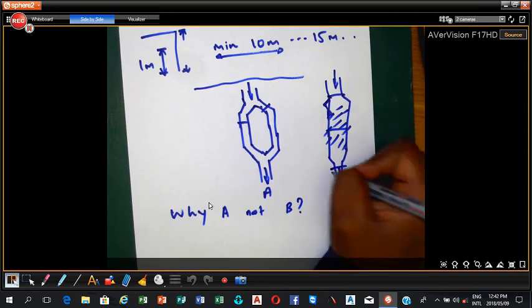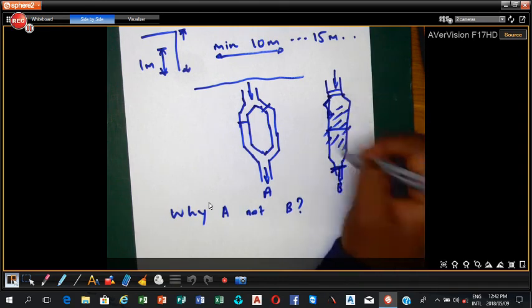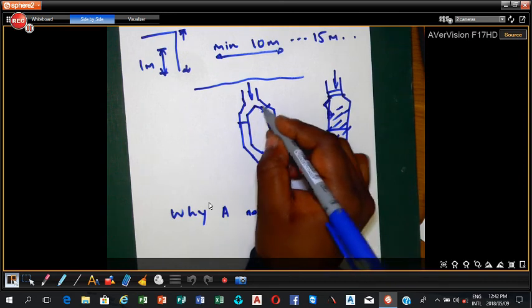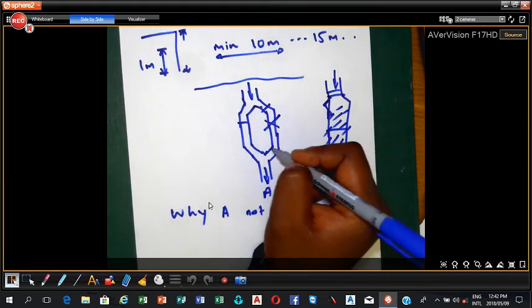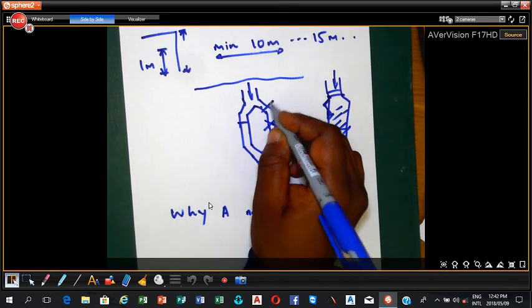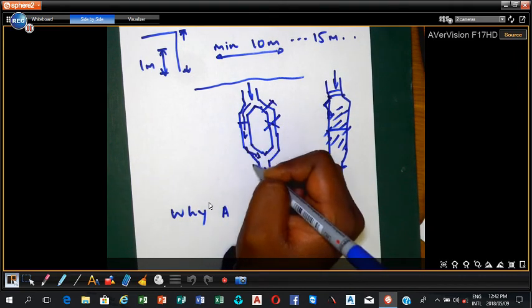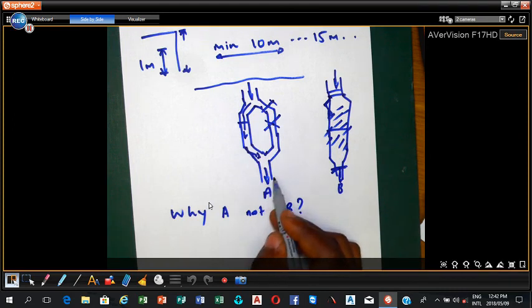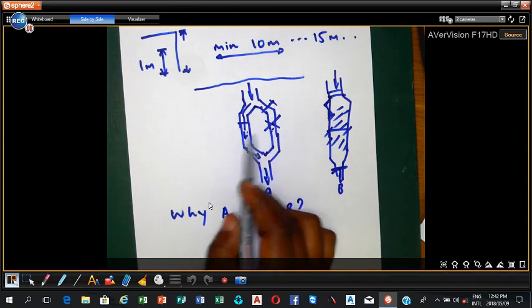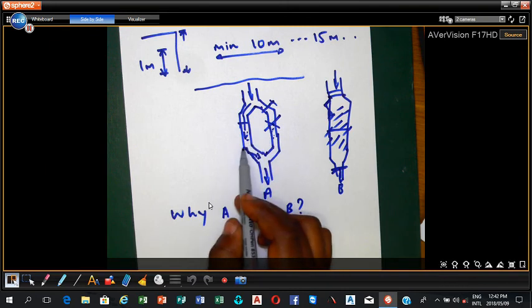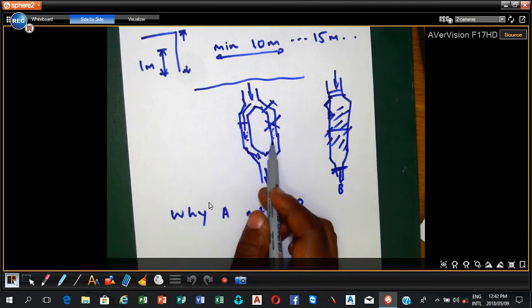There's no process going to take place within the grit channels. But in this context, if there is a problem here, then this one would be shut down, and the flow will be conveyed on the other side. In that context, the alternation best suits even the worst case scenarios when it comes to cleaning and maintenance.